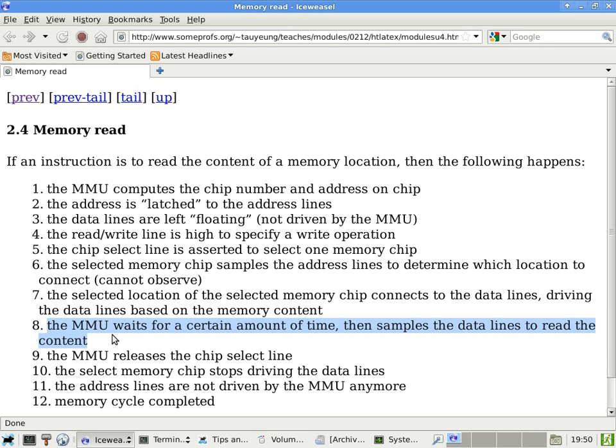When everything has to go out to the DIMMs, the dual inline memory modules, they have to go through this process. But before that they have to go to the memory chips, internal. All that stuff will happen before the MMU. Oh, I meant on the read. Does it go to the register straight from the MMU? The read operation can read straight into an ALU because the Intel processor allows you to specify a memory location as an operand. So it can go straight into the Y shape and feed the ALU directly. It does not have to go through a register first.